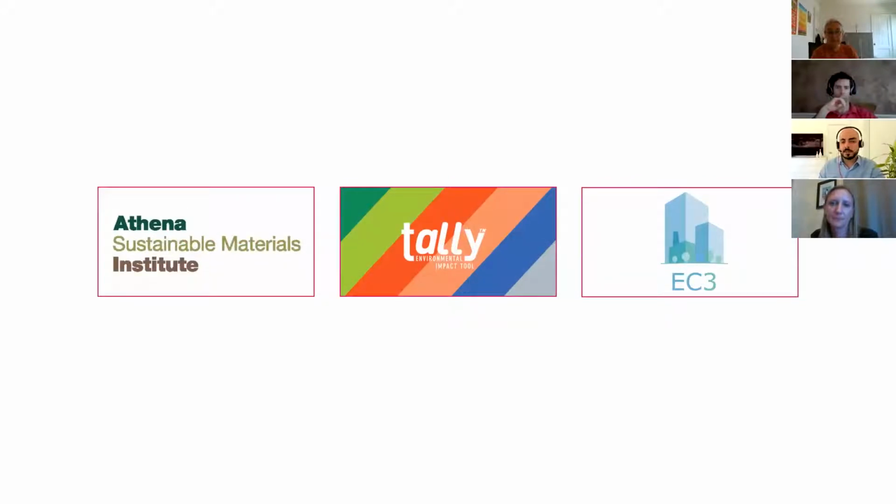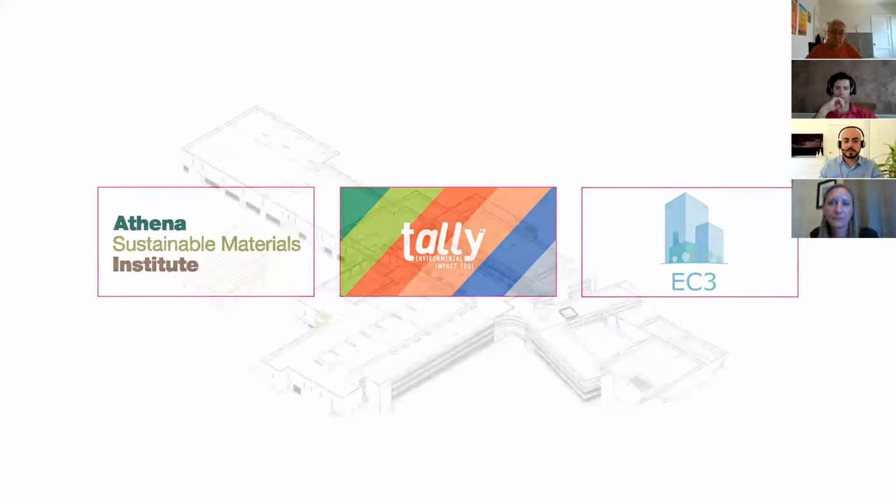In our workflow, we have a kind of palette of tools. Sometimes we start early with Athena, transition to Tally, where when we have a Revit model, we could get a little bit more detail into a Revit-based LCA. But our studies are still general, and let's say we're comparing concrete to another material. And Tally also enforces our LEED workflow for LCAs, and then we also use EC3 to get into product-specific data and optimizing product-specific data within a material.